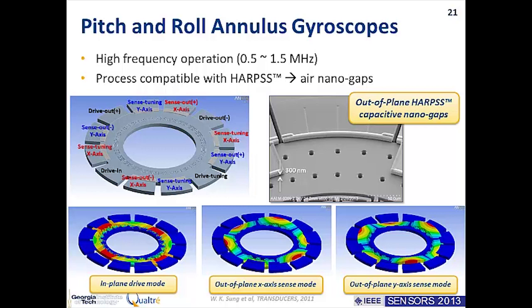Now, if you design this correctly, you can even place a Z-axis gyroscope right in the middle of that, and then you get a triaxial gyro in a very small area. If you have enough room there for it, we've done it in the past, and the problem is that then that Z-axis gyro might be way too small, and then you have a lot more variation with process. So if you have a better process, you can definitely do that.